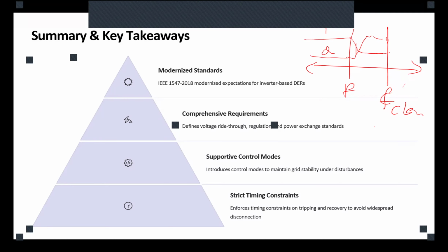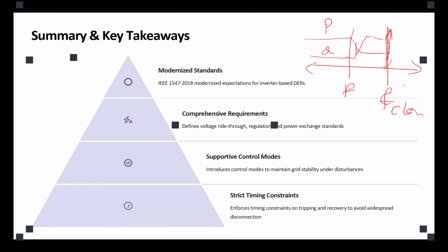When the fault is cleared, the system doesn't need that Q, so you need to increase the P. If you instantly increase the active power, the control system will see it as a rush of new current, which is the same situation as when you have a fault.